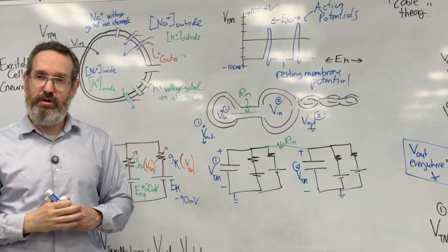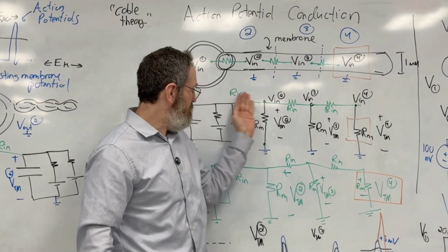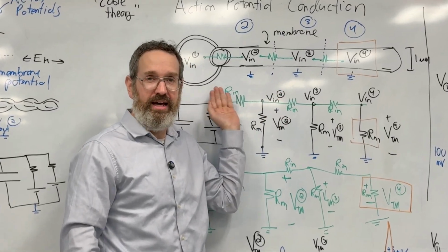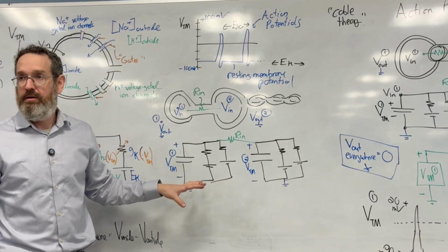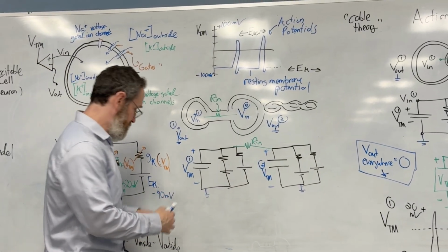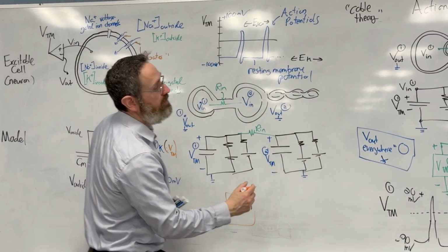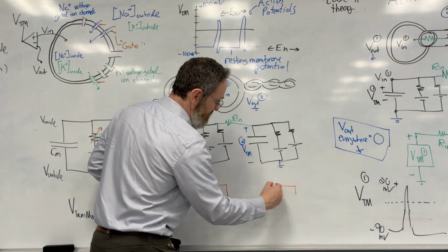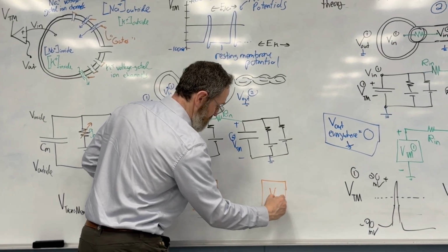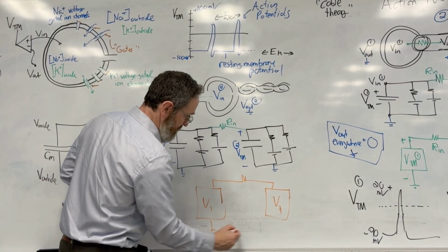I could have run the course, but I wanted to present it this way because I wanted to anchor you in voltage divider. Here it's a bit hard to see that this is a voltage divider, because you wouldn't think of all of this as our V1 and all of this as our V2, and they're connected like that.